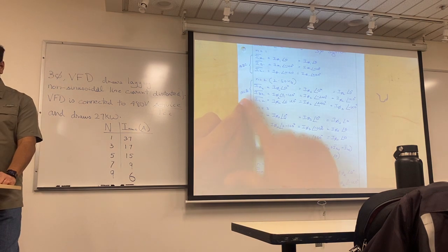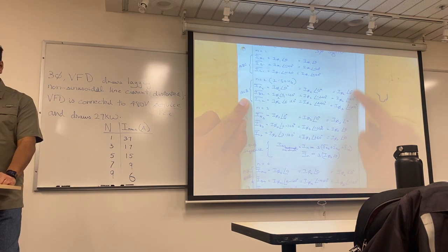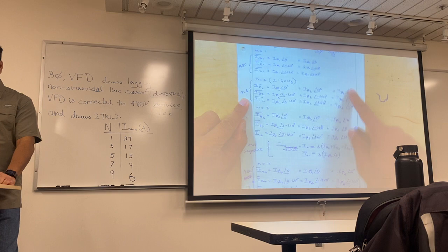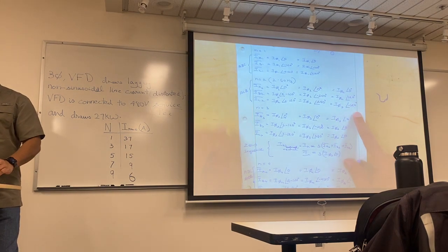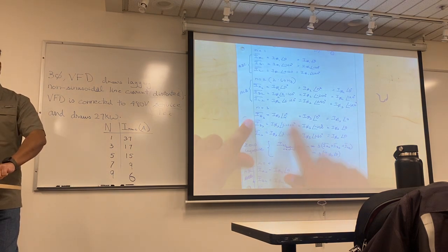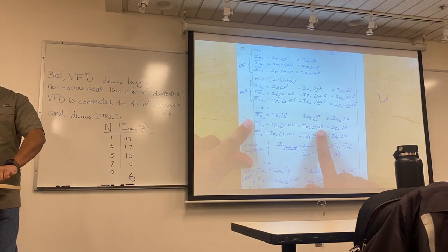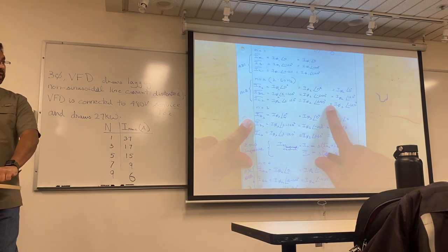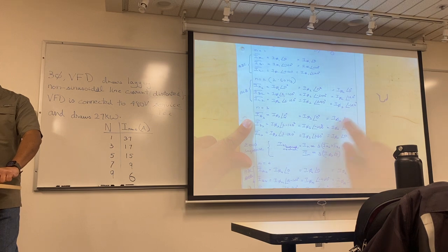Fortunately, this ACB is, again, when you do the numbers, sort of balanced because you have a 0, 120 and negative 120. Now going for the third harmonic, I do the same, 0, 3 times negative 120, 3 times 120. And when I multiply 3 times negative 120, I end up with a 360 with a negative sign, which is a whole circle, if you can see that. In other words, you end up with 3 currents, all with 0 degrees and all with the same phase.